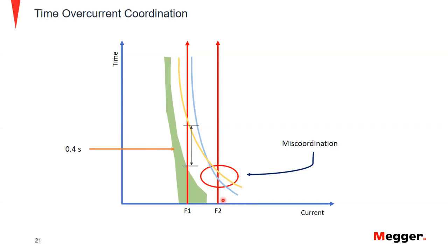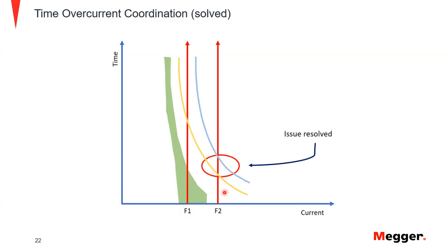So what we want to do is we need to fix this issue here. And how do we plan on doing that? Well, what we need to do is make sure that we go back to the main breaker and feeder time current curves. We need to adjust the settings, and we need these settings and also the curves to determine who needs to trip when. Right? So we need to establish the precedence like we were talking about earlier.